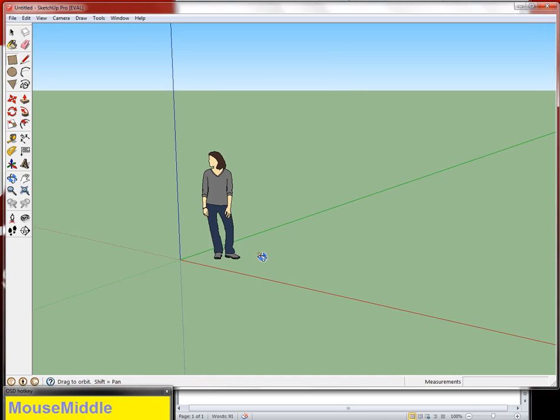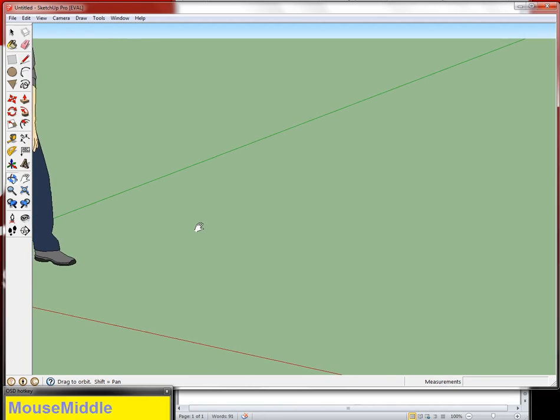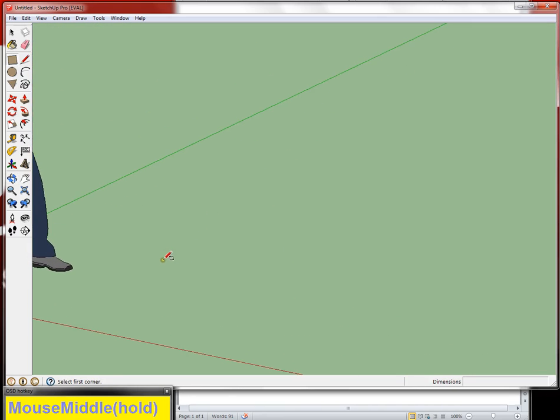I am just going to show you guys the actual building of the units because we go over using the tools in class. So I'm going to grab the rectangle tool, and I'm going to make an 18-inch by 18-inch square. I'm going to type 18, 18 and hit enter, and then I'm going to hit P for the push-pull tool. I could also come over here and grab it, but the more you get used to using keyboard shortcuts, the faster this will be.